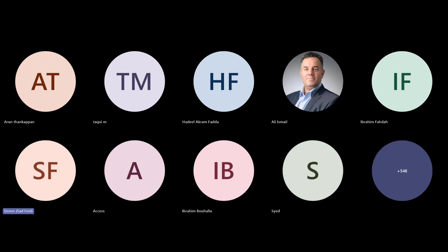Like I said, I highly doubt the number of floors will exceed 20 or 30, but the built-up area will apply here. If the built-up area is more than 30,000 square meters, then they should submit the structural model.